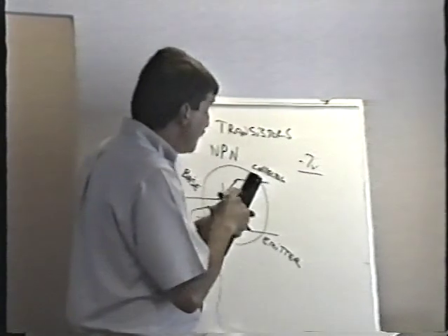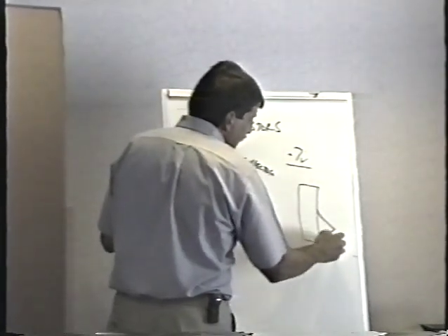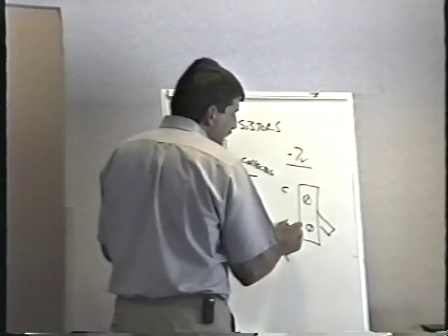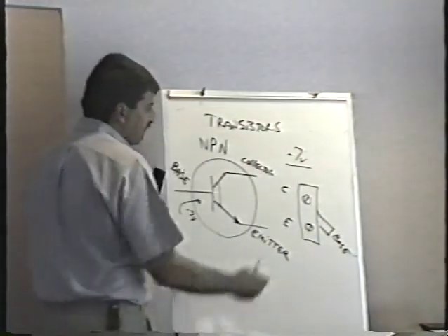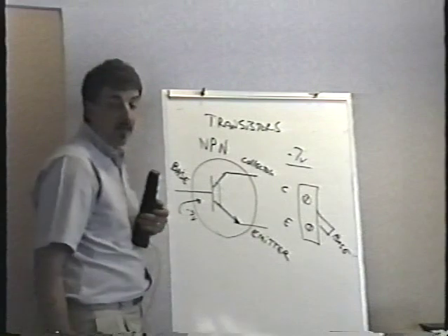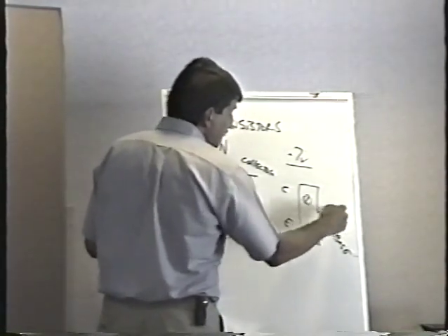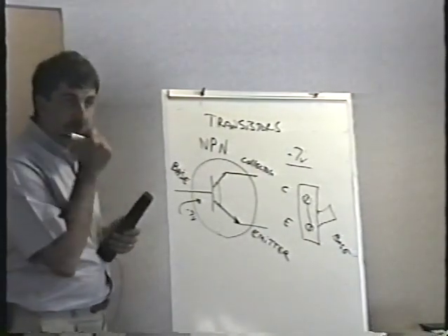So it's the same thing with transistors. When you think of a transistor, just think of it like a toggle switch here with the two screws. There's the collector, there's the emitter, the toggle is the base. When the transistor's off, there's no connection between the collector and emitter. All I do is flip the transistor on by putting 7/10 of a volt on the base, and those two are connected together, and that's all there is to it. Very, very simple.